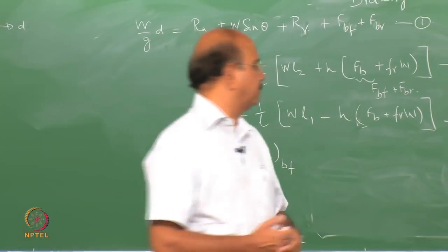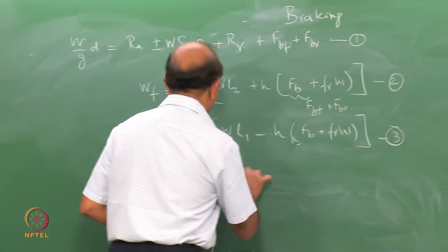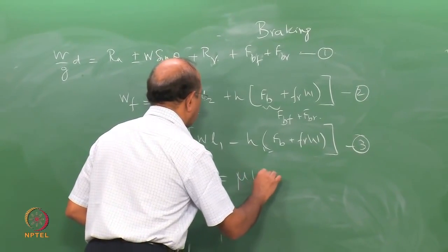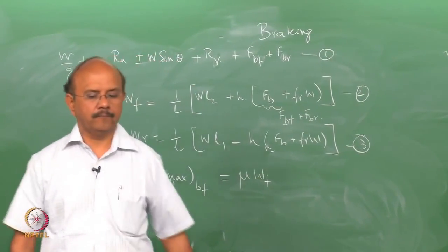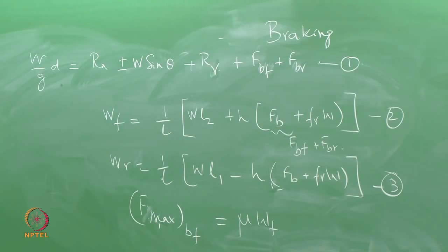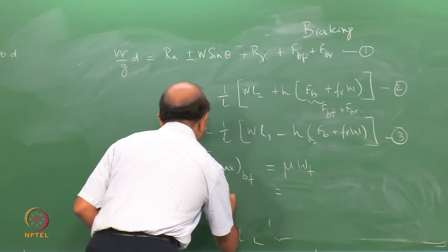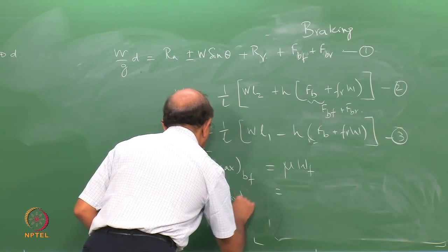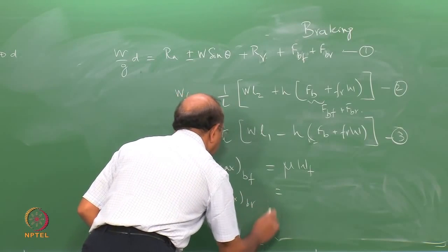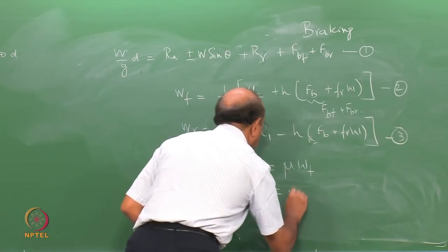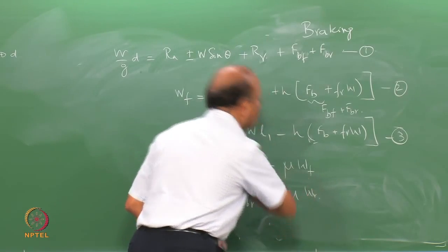You know this all the time, so that is equal to mu into Wf, and the maximum braking force at the rear is equal to mu into Wr.